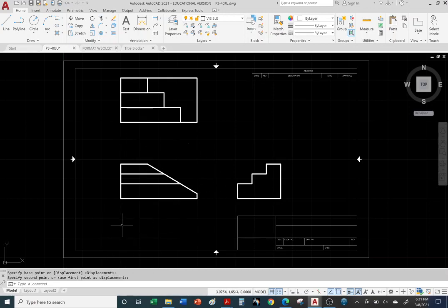So you have to put notes about how you are going to machine this. How are you going to label it with the part number? What type of material are you using? Are you going to paint this? Are you going to have some areas taped off before you paint? You're going to put all of this in your general notes.